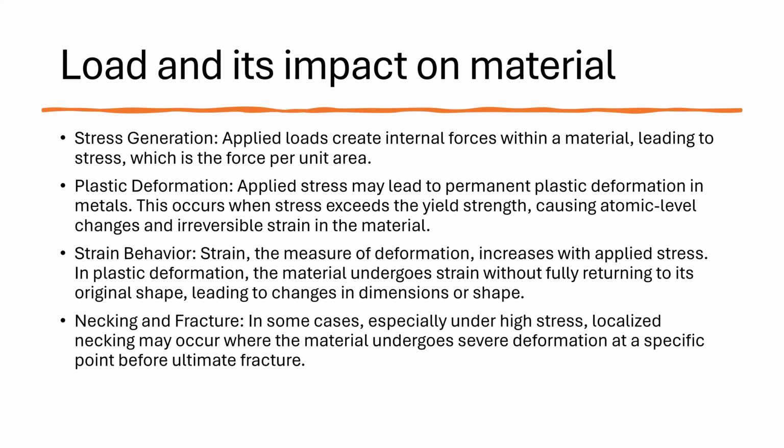Load and its impact on materials. Stress generation. Applied loads create internal forces within a material, leading to stress, which is force per unit area. Plastic deformation. Applied stress may lead to permanent plastic deformation in metals. This occurs when stress exceeds the yield strength, causing atomic level changes and irreversible strain in the material. Strain behavior. Strain, which is the measure of deformation, increases with applied stress.